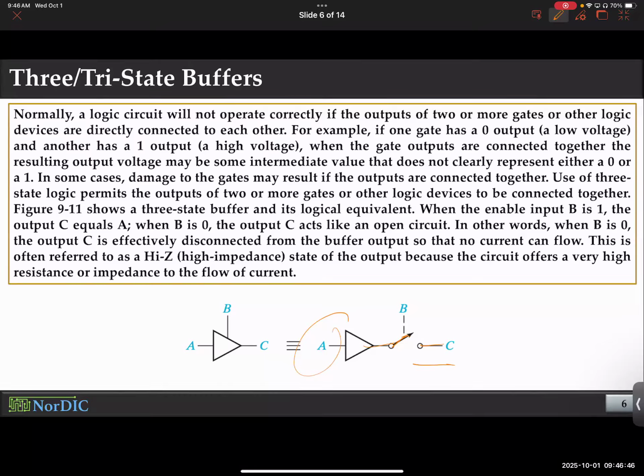So this is called a high impedance situation. It's also mentioned here. You can read it. In some textbooks, they call it high Z. Z represents impedance, so it's also known as the high impedance condition, right? What it means is essentially when you disconnect two nodes. If I cut a wire, what do I have in between these two branches? Air. What is air? An insulator. What does an insulator have? A very high resistance, or very high impedance, I can say. So essentially, disconnection represents high impedance. That's exactly what it is.